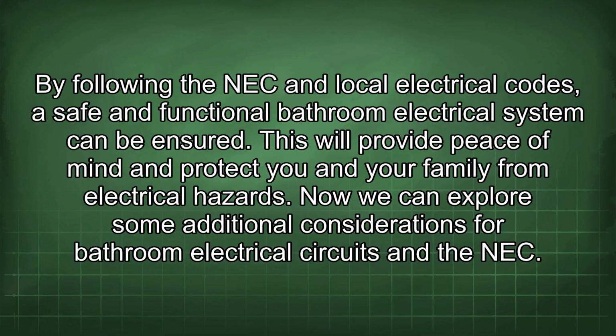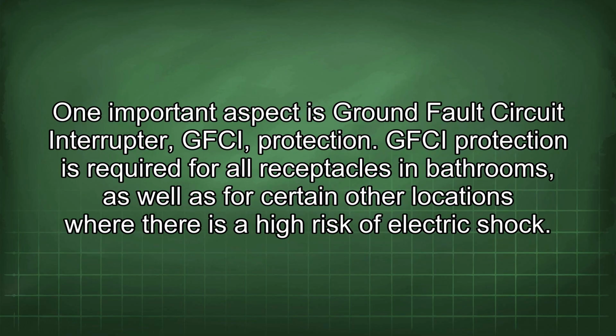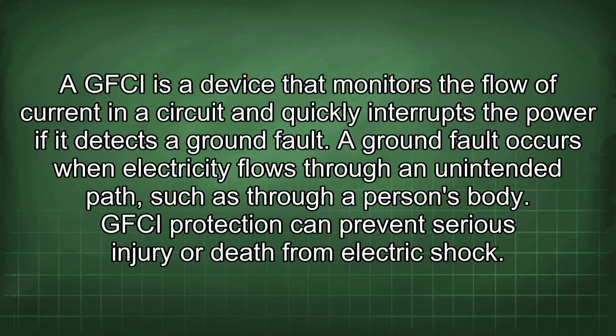Now we can explore some additional considerations for bathroom electrical circuits and the NEC. One important aspect is ground fault circuit interrupter, GFCI, protection. GFCI protection is required for all receptacles in bathrooms, as well as for certain other locations where there is a high risk of electric shock. A GFCI is a device that monitors the flow of current in a circuit and quickly interrupts the power if it detects a ground fault. A ground fault occurs when electricity flows through an unintended path, such as through a person's body. GFCI protection can prevent serious injury or death from electric shock.